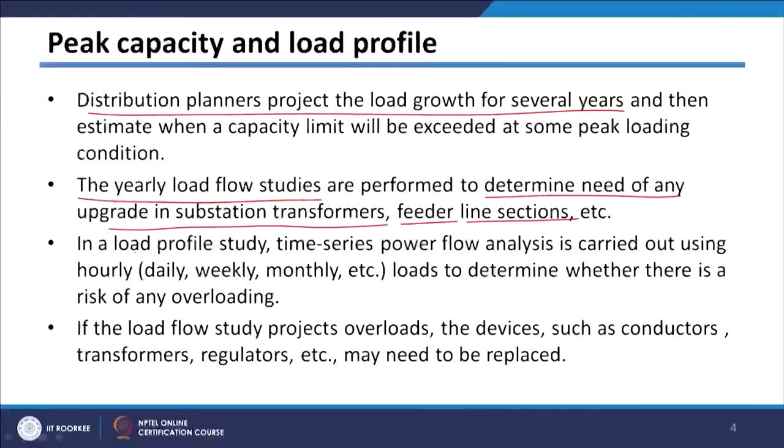Then in the case of load profile studies, time series load flow analysis is carried out. Time series load flow analysis is nothing but load flow analysis carried out at each time instant. Suppose we divide the whole day into 15 minute intervals, and load flow will be carried out at each 15 minutes, without considering the dynamics of the system.